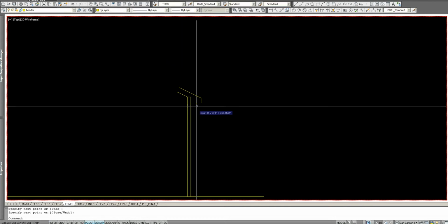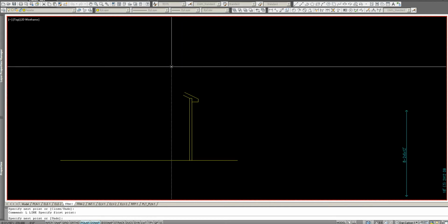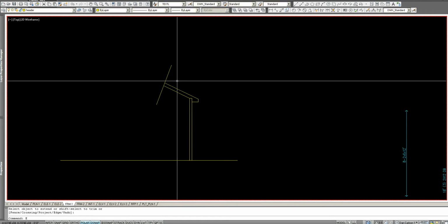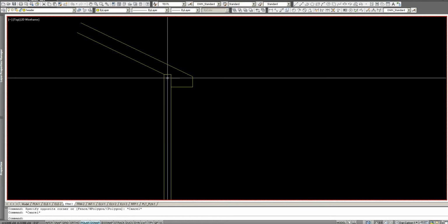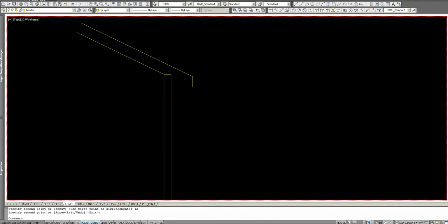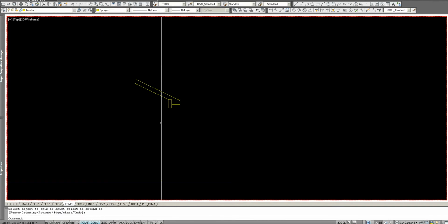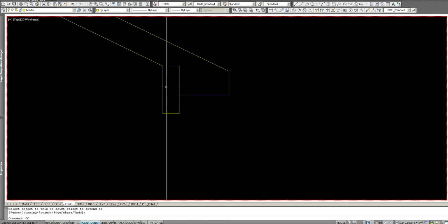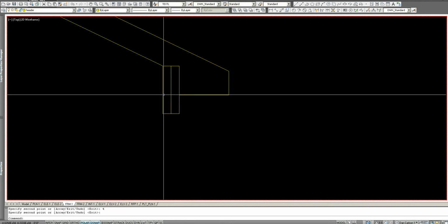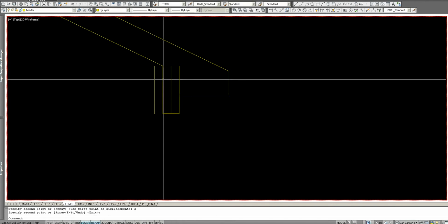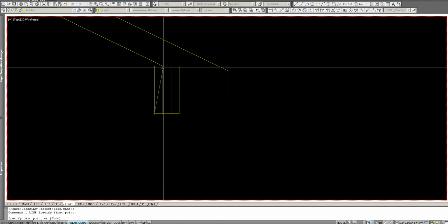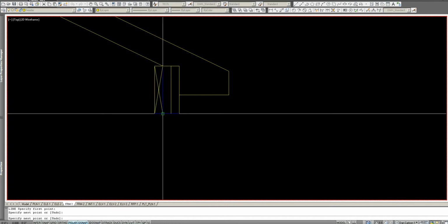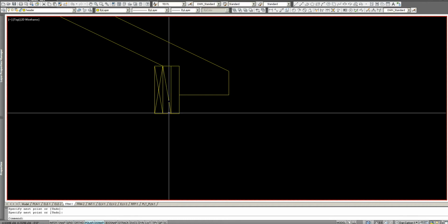That's our box, very very simple box soffit. Well, once it gets into this porch area here, it's just going to be a 2x12 beam, a triple 2x12. It's going to look like that. Okay. And it's actually going to be 3 of them, which lines up nicely with a 2x6 wall anyway.